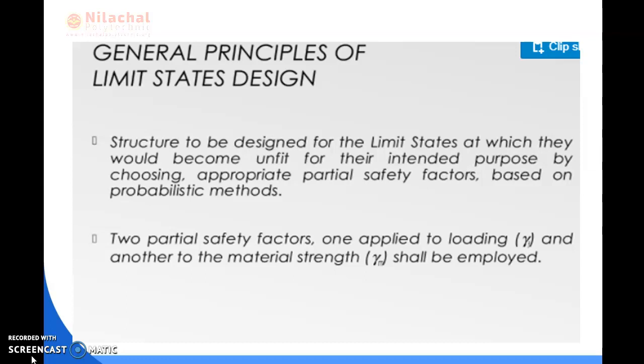Then we discuss the general principle of limit state design. Structures are to be designed for the limit state at which they would become unfit for their intended purpose, by choosing appropriate partial safety factors based on the probabilistic method. So in limit state design we consider the partial safety factor, which we already discussed in chapter 1, the difference between the working stress and limit state methods.